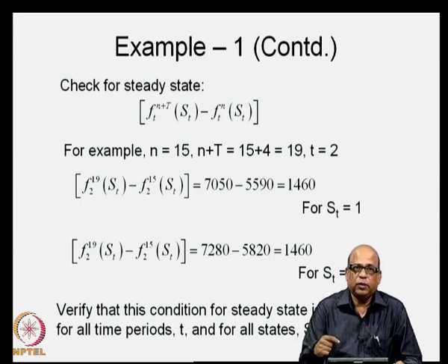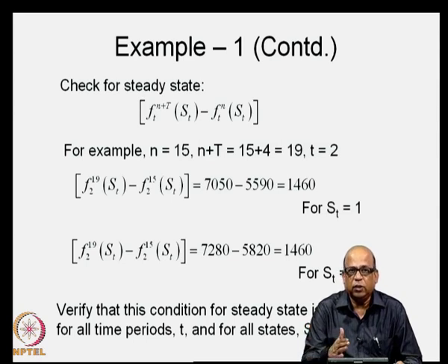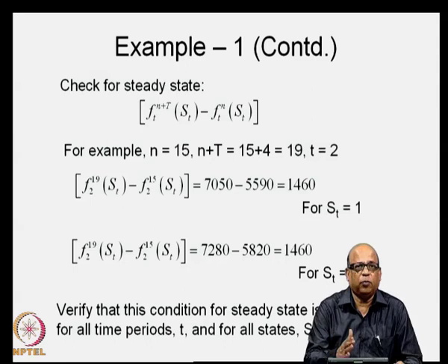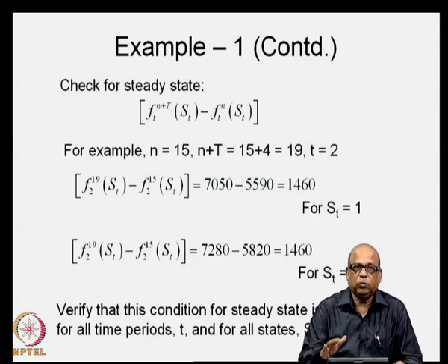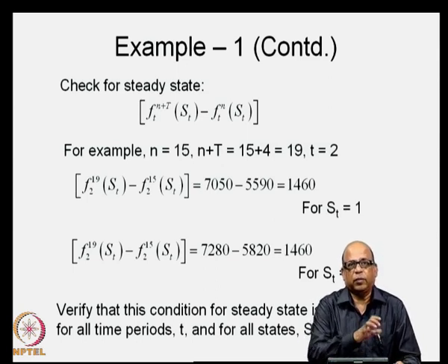If your inflows were changing from one year to another year, let us say that you were solving it for 10 years and every year the inflow pattern was changing, then at the end of the 10 years you will not get to a steady state policy. You are able to achieve the steady state, remember, I repeat, only because the inflow pattern remains the same.